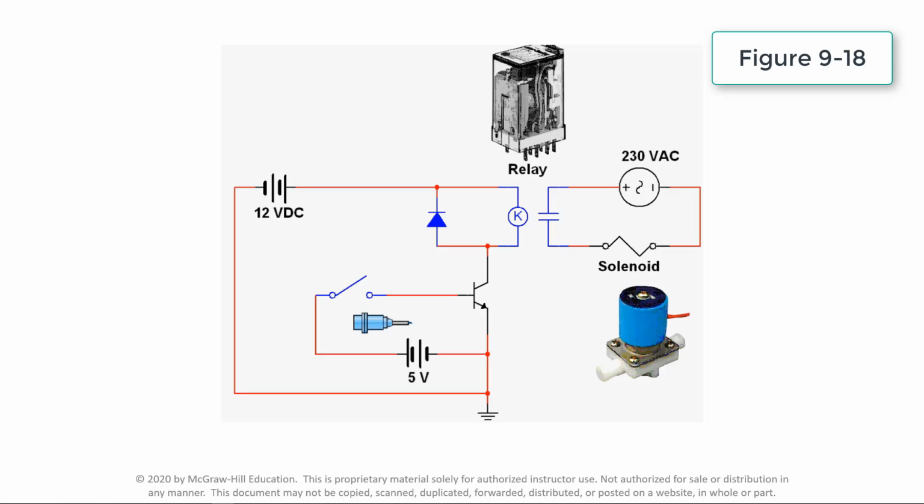When the transistor is in the on state, collector current is at its maximum value, and the voltage across the collector and emitter drops to near zero, while that across the relay coil increases to approximately 12 volts. Note that the clamping diode is connected in reverse bias across the relay coil and prevents the induced voltage at turnoff from becoming high enough to damage the transistor.